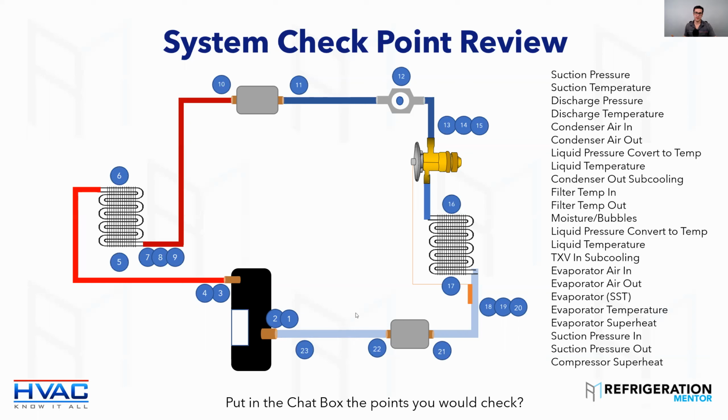And then compressor superheat. Oh man, this is probably the most important check, the return gas temperature check to the compressor. Most technicians take it, but they don't know what to do with it. You need to understand, if I take a temperature at, say, 18 here, and then I take a temperature at 23, you need to understand if this temperature is way higher, why?